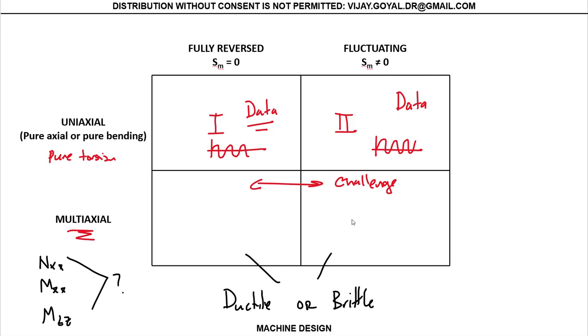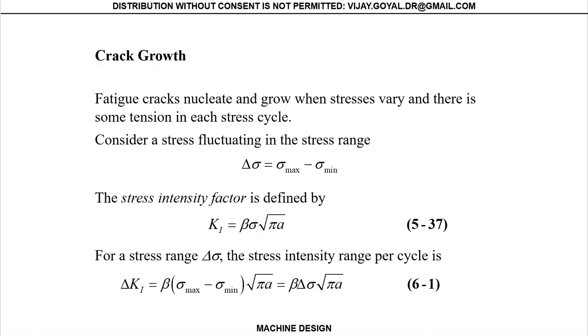Okay. So before we move on any further and we keep on talking about these theories, let's understand a few things here. First of all, as I started our discussion, everything talks about crack growth. Okay, so it's nothing else than fracture mechanics, but fluctuating. When you fluctuate your load, then what's going to happen is your stress intensity factor is going to fluctuate, right?